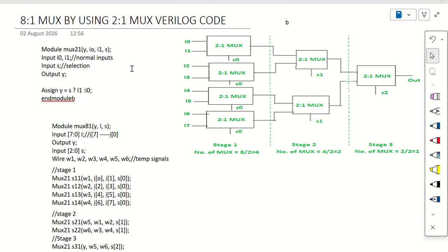If we have multiple inputs, we can process only a single input out of them, depending on the selection. Here we may have two inputs, four inputs, eight inputs, or 16 inputs, always a power of two. Out of the multiple inputs present in this circuit, you can select only one input at a time, depending on our selection inputs. That's why it is called a data selector.